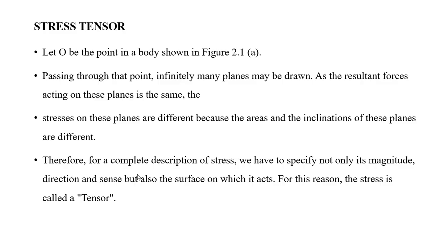Therefore, for a complete description of the stress, we have to specify not only the magnitude, direction and sense, but also the surface on which it acts. Sense is nothing but the direction of the force, whether you are applying it in the negative or positive direction. In the case of a tensor, we take the surface on which it is acting into consideration.